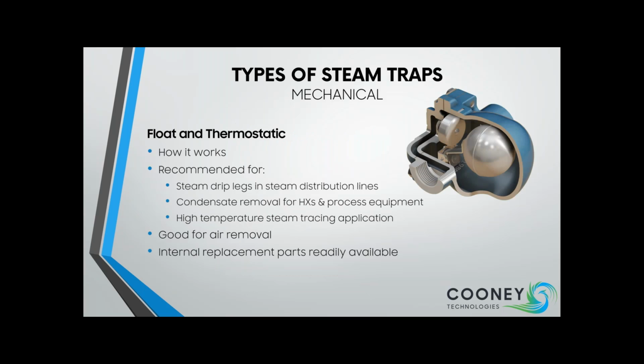That leads us on to the steam traps. Basically, the best way to get rid of condensate and air in a steam system is by use of steam traps. A steam trap is an automatic control valve that removes the condensate and the air from a steam system, and prevents the loss of live steam in doing that. First, we look at two types of mechanical traps.